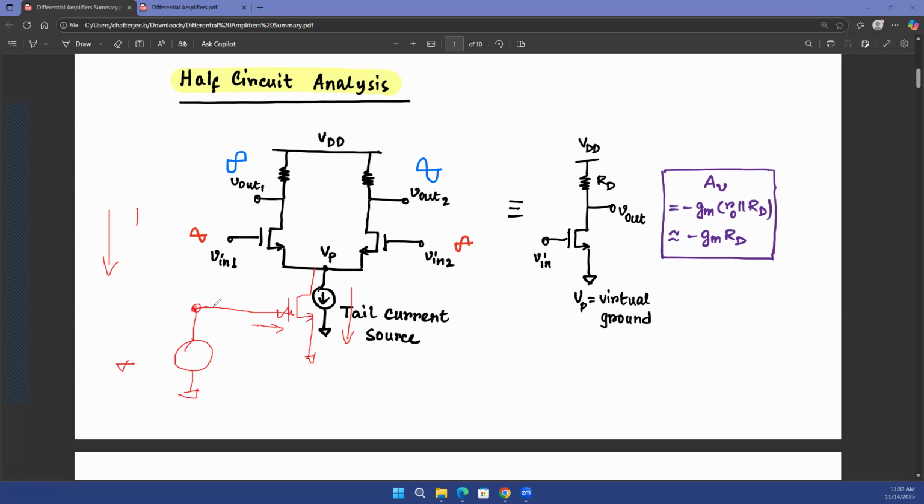So that means there is some small current through the gate, and then this path will have some amount of resistance. That means if I'm applying a voltage, let's say 500 millivolt here, what I may see at the actual gate of the transistor may not be 500 millivolt. It could be something different because of the voltage drop on this resistance, which is just the line resistance or the wire resistance.